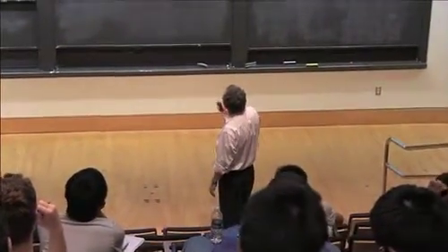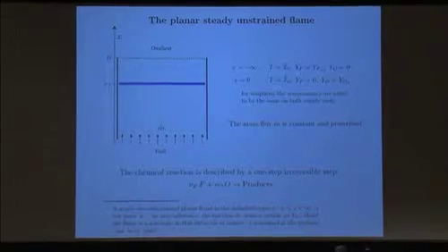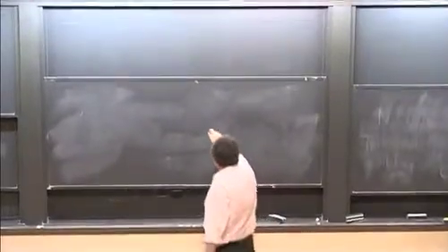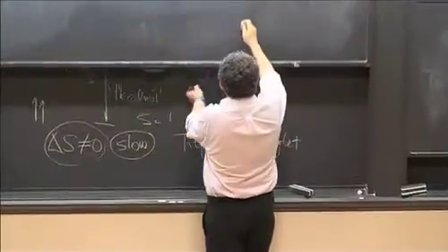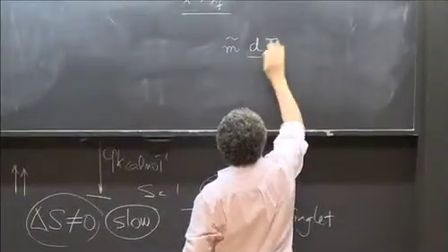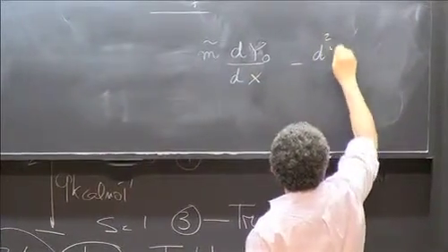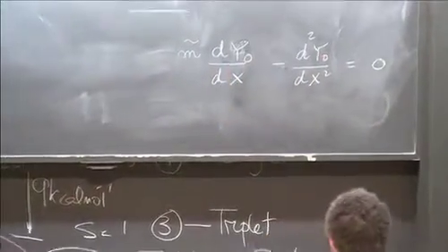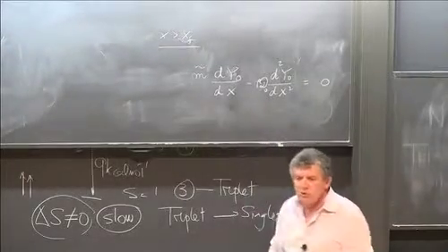In fact, the question is, why should I move this boundary to infinity? Well, you will not get a mathematical solution, and the reason for this is very simple. Suppose that you have such a flame, then beyond the flame, namely on the side which is x bigger than xf, your problem is going to be solving a convective diffusive problem, and I'm writing this for the oxidizer, equal to 0, because reaction occurs only in the blue region.